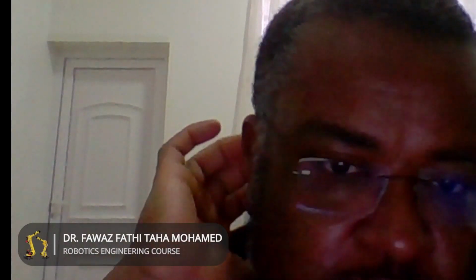Or I can represent this as a rotation around fixed axes with pre-multiplication. Firstly, I will rotate around the fixed z-axis with 10 degrees, then a rotation around the y-axis with 50 degrees, then 30 degrees. Here we will obtain the result. Continue, where this time we have specified the rotation angle in degrees.